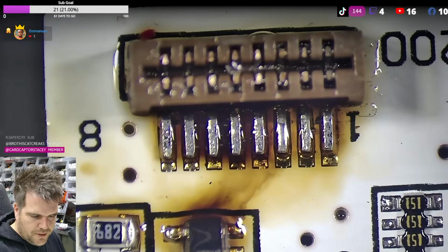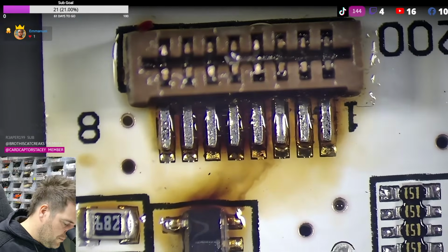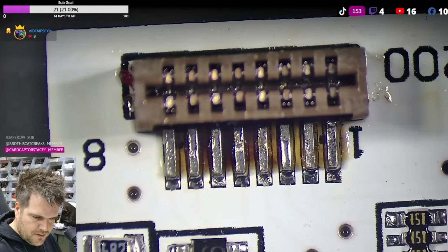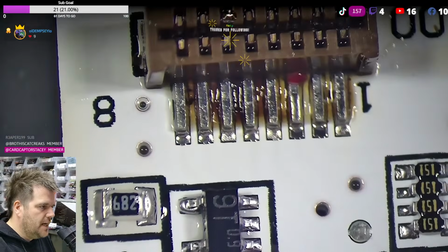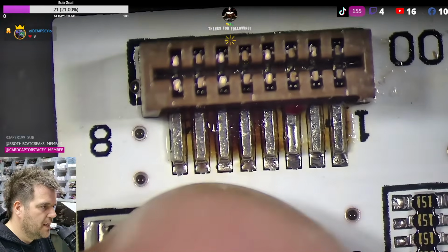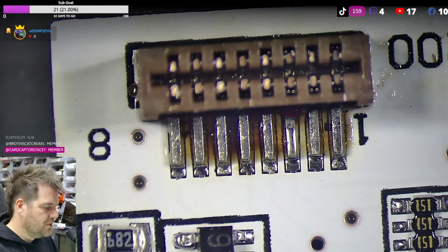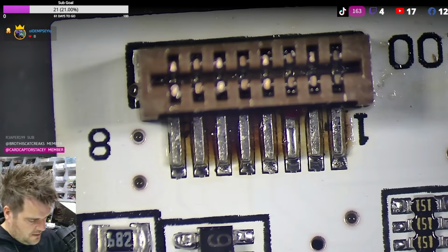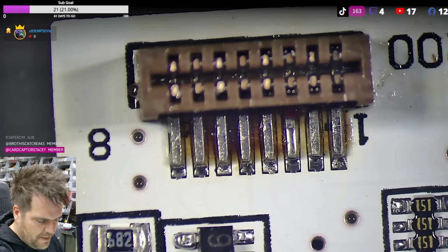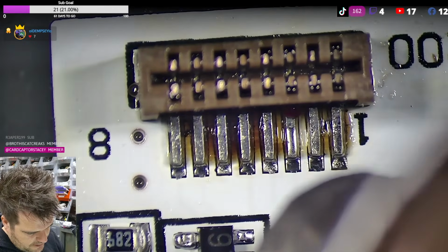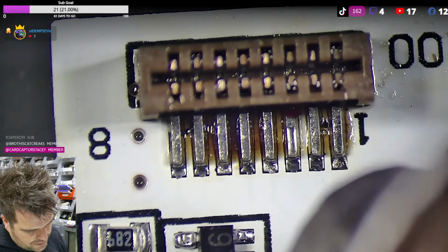And the important part here is you need to make sure you put plenty of solder on, because that's why people avoid it, they don't want to put solder on because you get bridges. But you really need to put the solder on to get these nice formed connections. So see how we've got nice balls now, like nice flowed pins. If you don't put plenty of solder on, you won't get them pins to flow nice, and the joints will still work, but they wouldn't be as nice, basically. So flood it with solder first, get your connections all good.